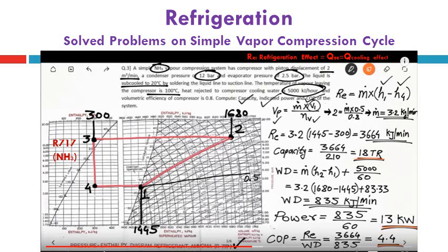Also the effect of subcooling degrees inside the condenser at its final stages is to increase the amount of cooling effect rather than the increasing of the COP, due to the reducing of the condenser pressure when using cooling water, which has the effect to reduce the work of the compressor and reduce H2 if compared with air cooling systems.